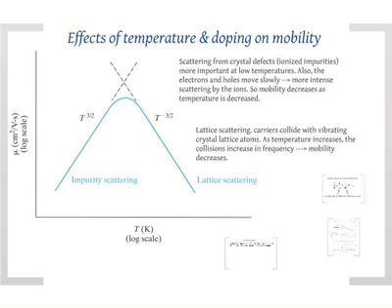At low temperatures, what's important is primarily scattering from crystal defects. If there are charged donor atoms or acceptor atoms, or crystal defects like a missing atom, or ionized impurities, the charges will scatter from these charges. At very low temperatures, it's not the motion that's important, but just the charge interactions. And due to the fact that at low temperatures the electrons and holes move very slowly, any collision is much more important.